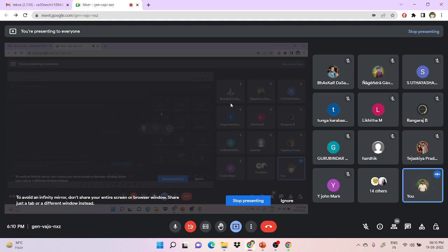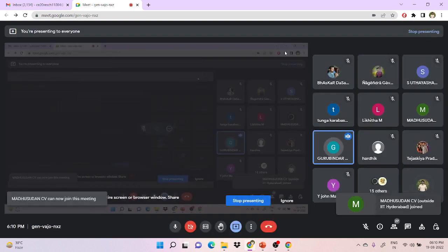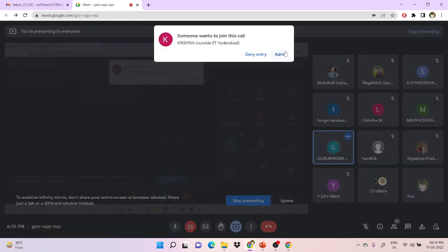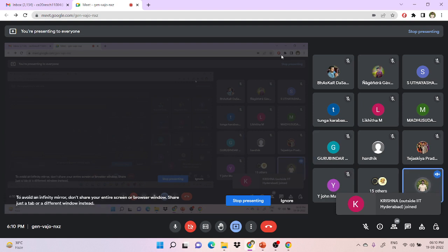So anyone else wants to add anything? BOD is used to measure the content of organic matter in wastewater, and COD is used to measure the quantity of oxygen required for the biodegradable organic process. Yeah, you have said it correctly. But in COD, you generally measure biodegradable and non-biodegradable both, while in BOD only degradable organic matter.